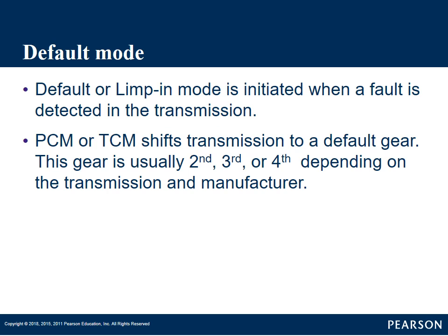I have seen it more often than not because technicians are terrified of an automatic transmission. One's in a default and it's got a code in it, like say a gear ratio code. They just automatically say, well, the transmission must not be any good. So they put a remanufactured transmission in it, and because that new transmission came with all new sensors, it shifts just fine and they think, oh, I fixed it. When it might have been just something as simple as a solenoid or a speed sensor.